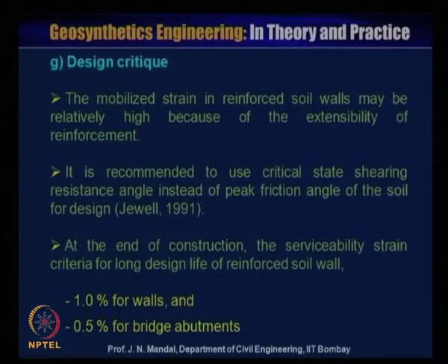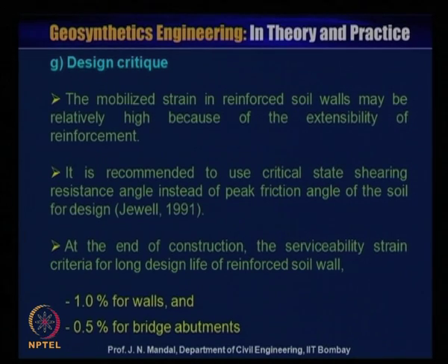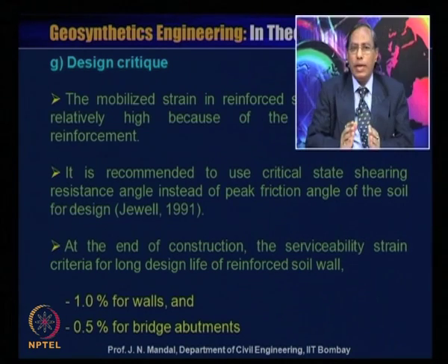Now, design critique: the mobilized strain in a reinforced soil wall may be relatively high because of the extensibility of reinforcement. It is recommended to use the critical state shearing resistance angle instead of the peak friction angle of the soil for design. That is Jewell 1991. At the end of the construction, the serviceability strain criteria for long design life of a reinforced soil wall is 1.0% for the wall and 0.5% for bridge abutment.